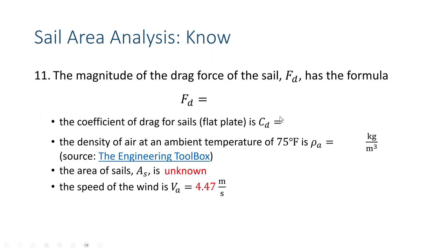The magnitude of the drag force of the sail, well, we know what this equation is. Think about it for just a minute and see if you can come up with this force of drag equation off the top of your head. We've seen it a few times now. I think this will be the third time that we've formally discussed it in class. Okay, so if you said 1/2 times the drag coefficient times the density of air, because that's what the sail is catching and experiencing, times the area of the sail times the velocity of the air squared.